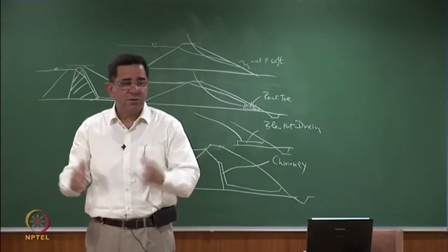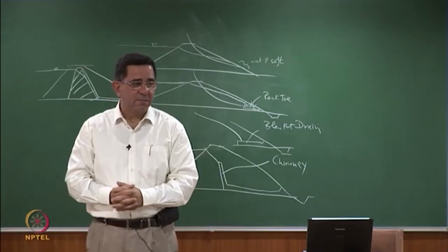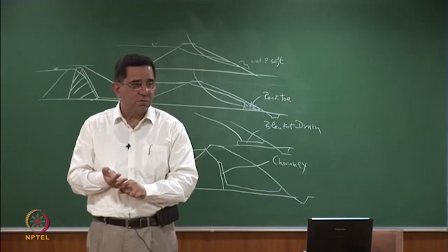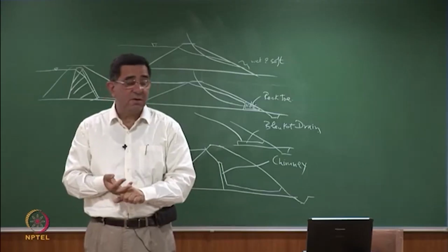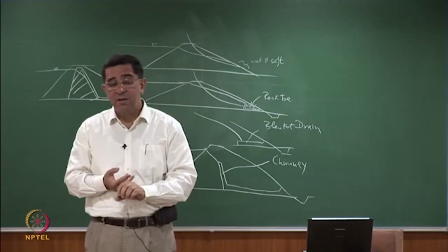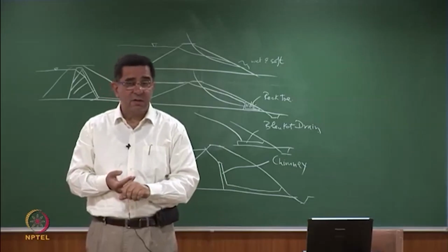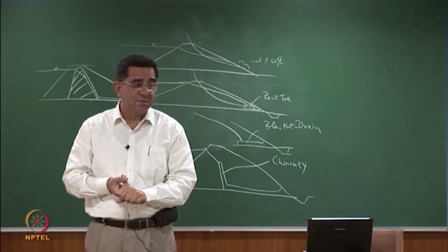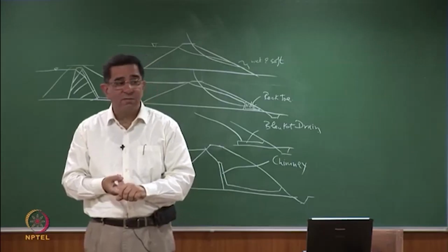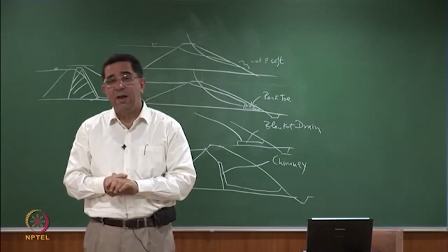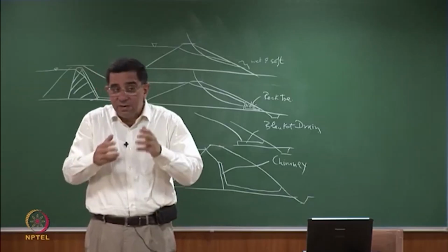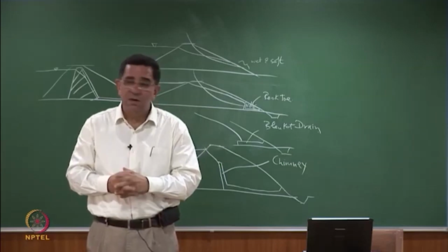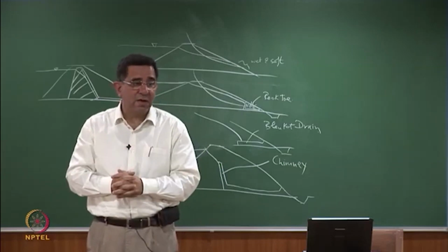But if you have any questions, I'll be happy to answer. So we've seen what are the different layouts or plan views of the ponds. We've seen how we raise them incrementally. We have identified the critical issues in the stability analysis. We have recognized the role of the phreatic line being very critical to stability, and how the internal drains keep the phreatic line away from the downstream face, and as long as we do a good design, it's fine.